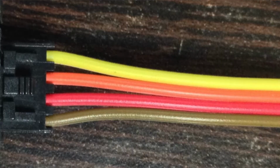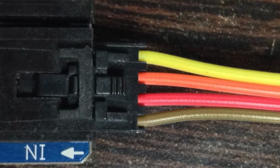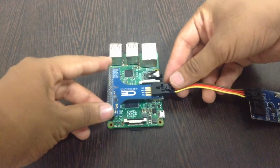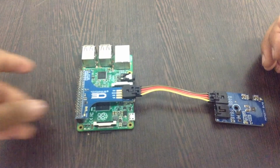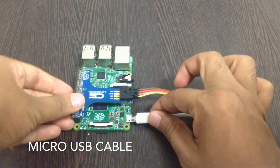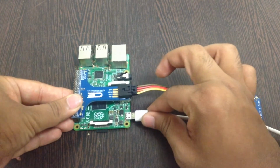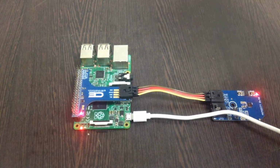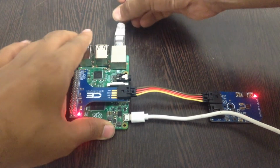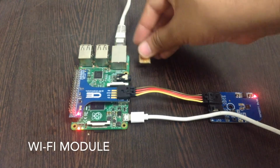Now to connect this sensor with Raspberry Pi, we have an I2C connecting cable. While making connections with the sensor, please make sure that the brown cable goes inside the ground of the sensor this way, and similarly to the I2C shield. Now to provide power to the Raspberry Pi, we have a micro USB. Let's power it up. We provide internet to Raspberry Pi using a LAN cable, or we may also use a Wi-Fi adapter.